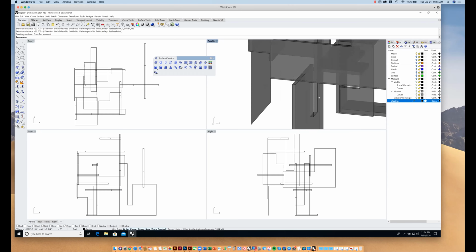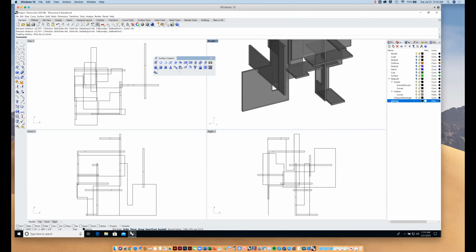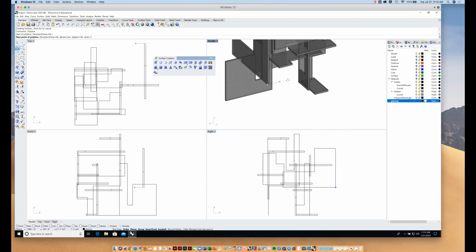I'll do that again, maybe somewhere else. Yeah, why not? I'll do that over here. So I'm going to go ahead and make a line. I'll click on this corner, like I'll snap to the endpoint. I have my ortho set on, right? So I can only draw 90 degrees from that. So I'll draw on the x-axis. I'm going to type in a distance this time. This is just like drawing in top view. I know my curtain wall is going to be in 4-inch modules, so let's make this 16 feet.